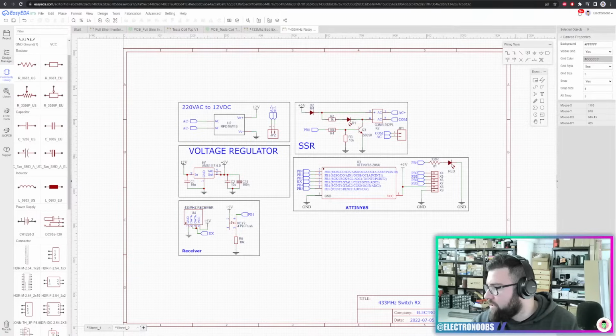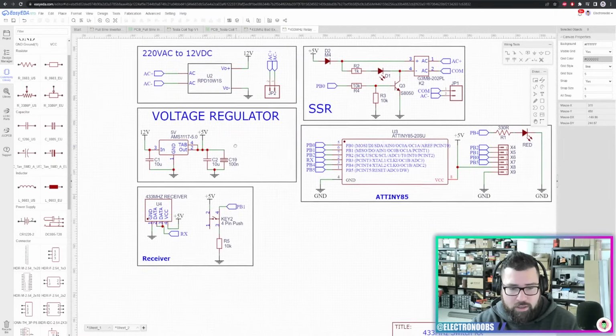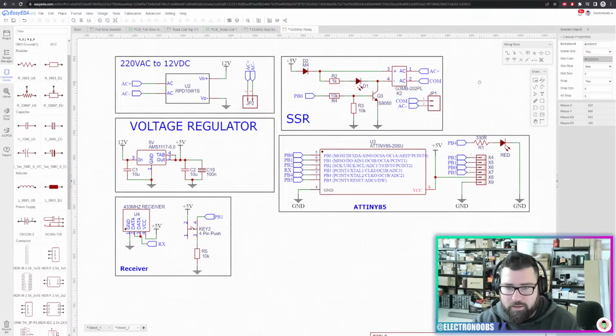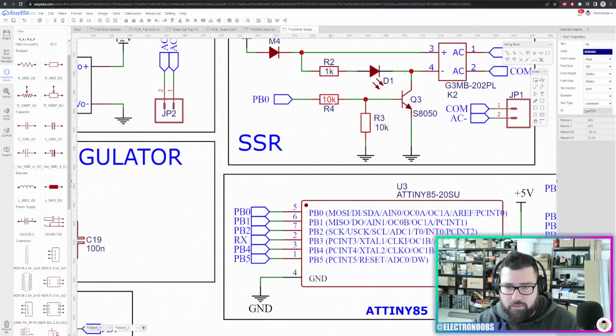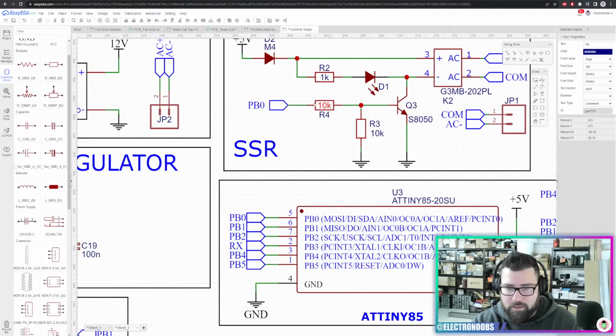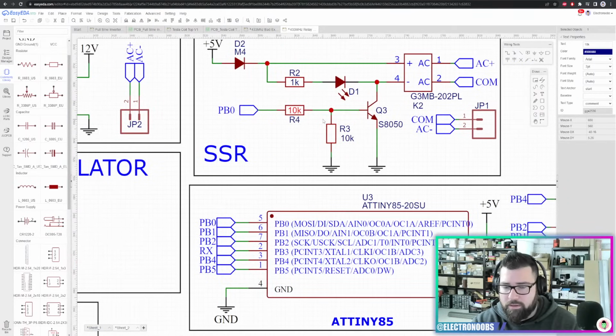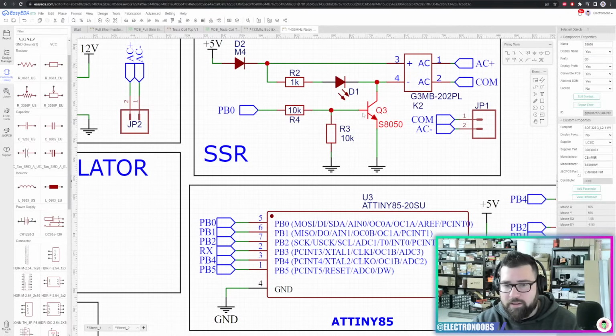You've created a voltage divider with R3 and R4, so the base resistor is also sinking current into R3 when high. R3 and R4, where are you seeing that? R3 and R4. Okay, this is a voltage divider. I wanted a voltage divider.